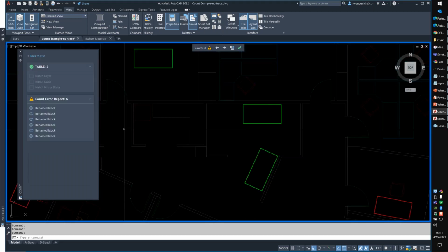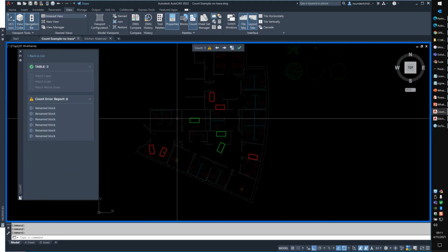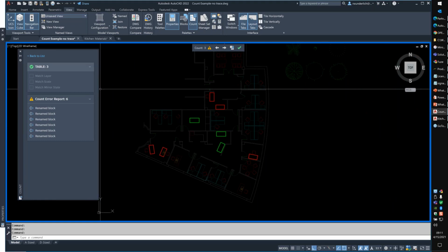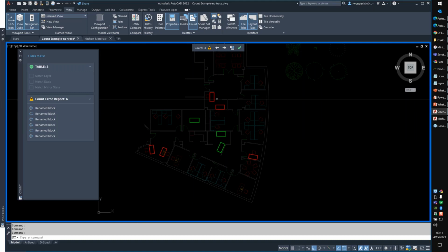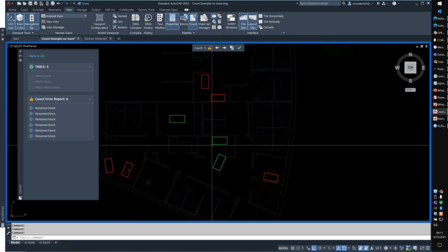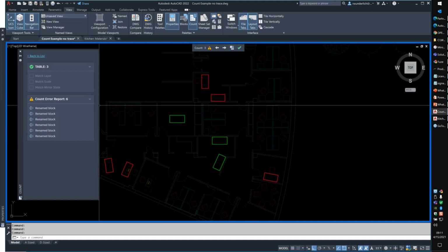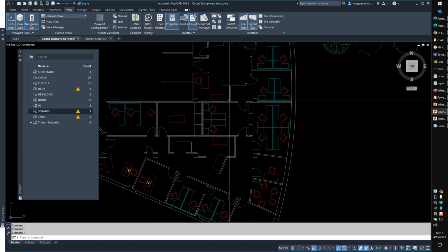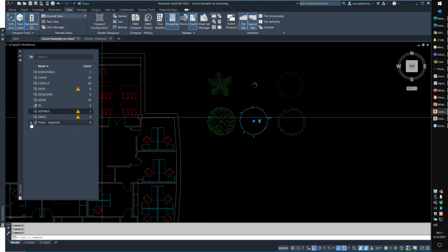And we go back to our list and we do the same thing with table, and you're going to see that it thinks that I have 3 blocks here, 3 tables, those are the green, and then it shows 6 renamed blocks. And actually these blocks are different blocks, but it's actually picking up the geometry and thinking it's pretty close, and so then it flags that internally. The other thing I want to show you here is that I've got 6 dynamic blocks in here, and then if I expand out this tree's imperial, you'll actually see that I see the view state of each of those.